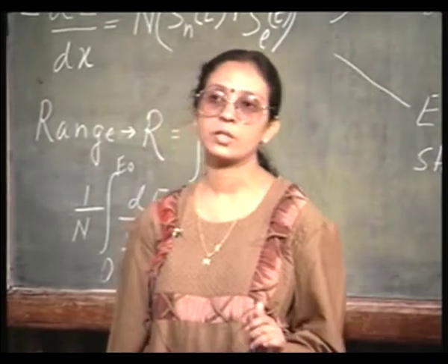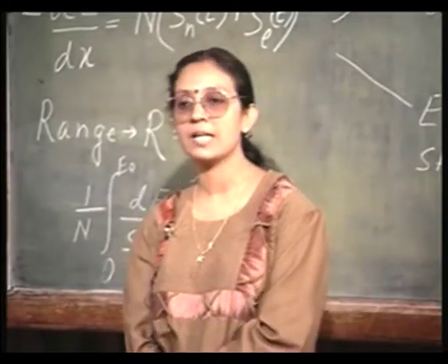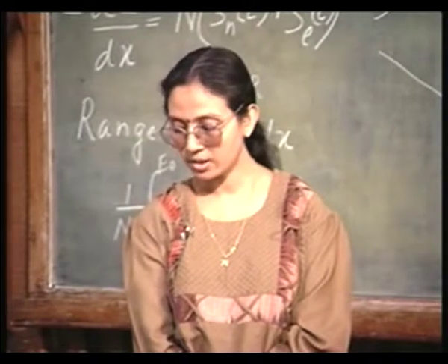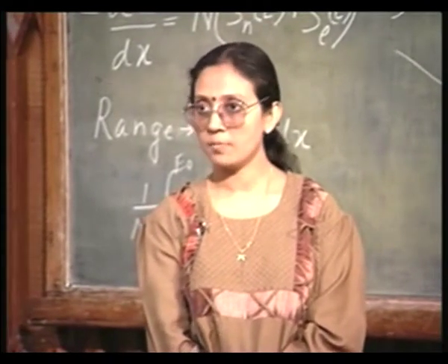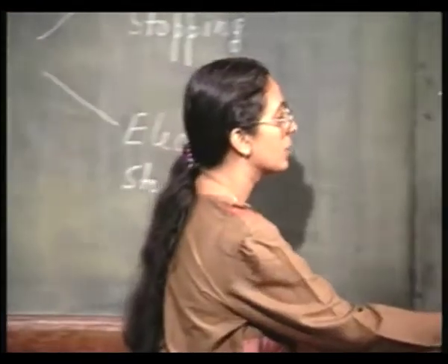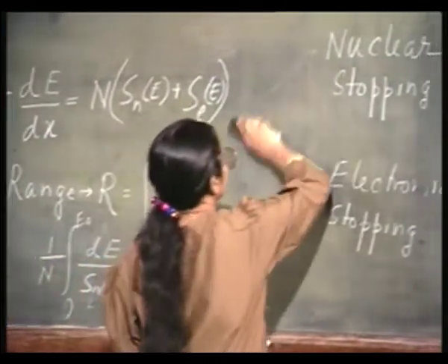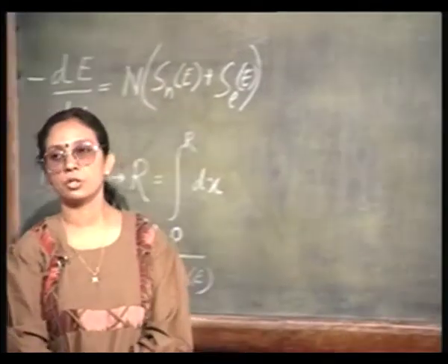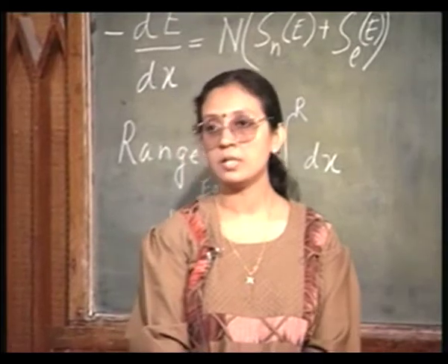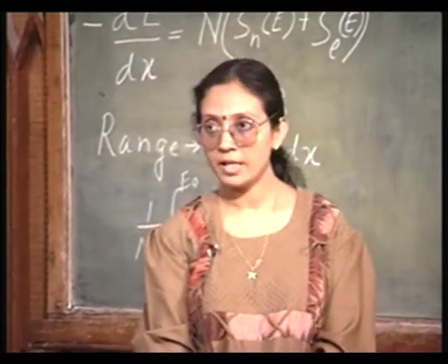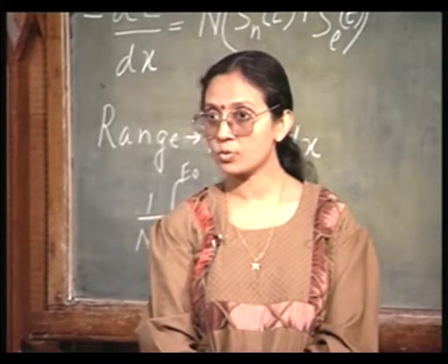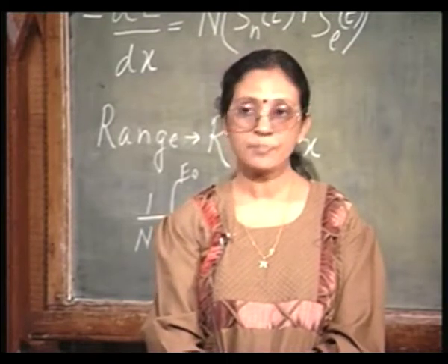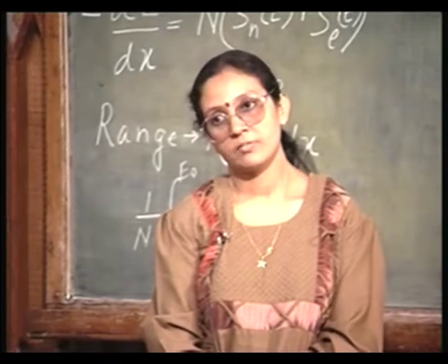Okay. But before that, what I want to do is, assuming that this is an amorphous target and assuming that this is a Gaussian function, calculate the dose, that is the total impurity concentration, the junction depth, and so on. So, if you want to calculate these things, you already know that the dose or the total impurity put inside the semiconductor is given simply by the area under the n versus x curve, right. Even in case of diffusion, you have seen that it will be simply given as the area under the n versus x curve. In other words, I have to integrate the nx from minus infinity to plus infinity.